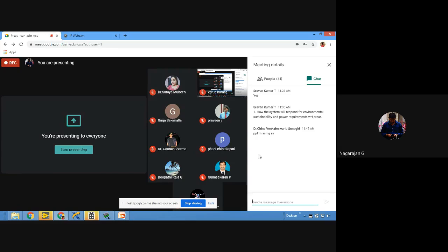It grabs the image, acquires it, processes the image, finds the dimension, and based on the dimension it gives a command to the servo, and when the bearing falls it is directly stored in the respective place. See, this is how fast your system is working. This is a small example of a real-time application which they have built with the help of this compact Rio system.